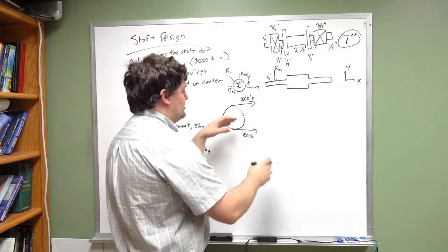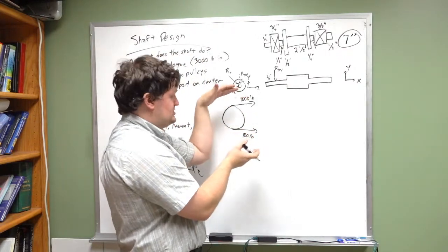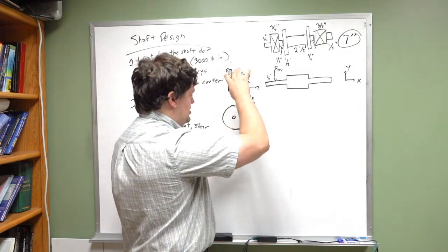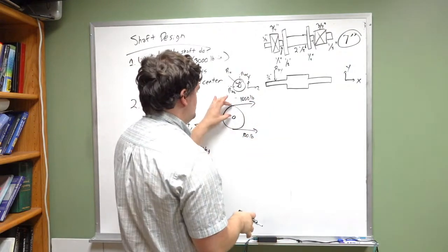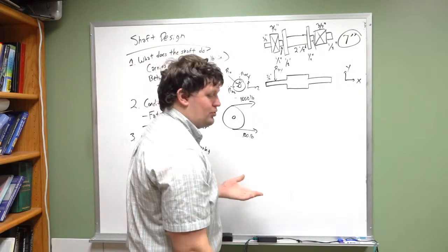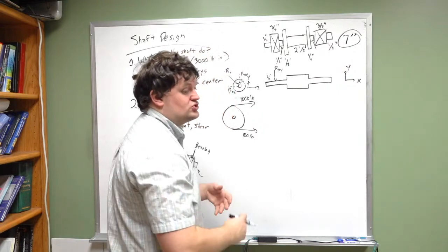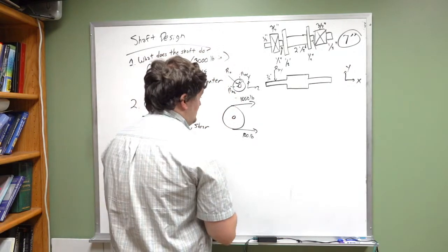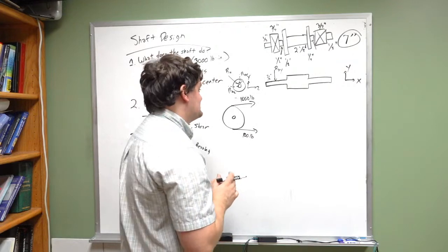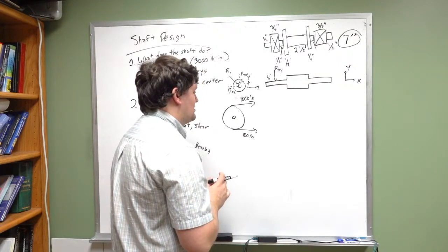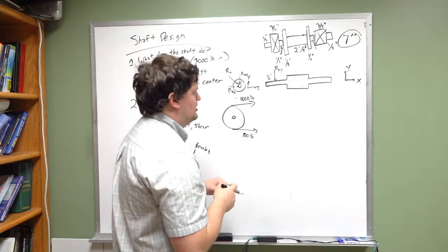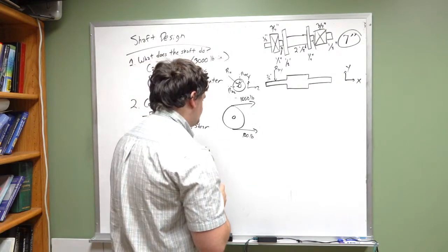That's going to give a net total between these two forces of 1,500 pounds. 1,500 pounds at 2 inches away from the center of the pulley, which means that is 3,000 pound-inches, which is a whole lot of torque. Usually you do not use pulleys for transmitting that kind of torque because it's just a ridiculous amount of torque. Pulleys are generally used for smaller force values, but we'll ignore that for right now.